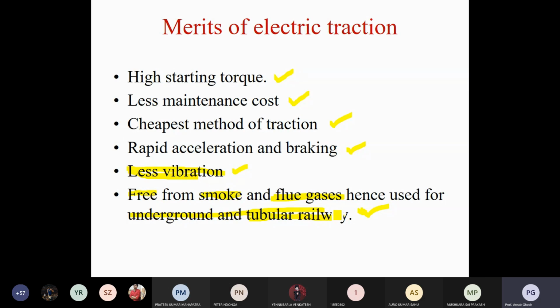In metro rail, in the Indian convention, metro rails are running in different cities, but their configuration is different as per the city. In Calcutta they are using 750-volt DC in the metro rail. But in Delhi metro, the overhead line is 25 kV AC, and they need to convert it to DC. So as per the city, the configuration is changed.